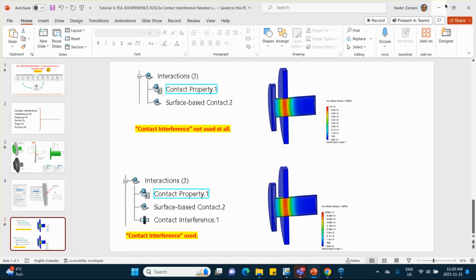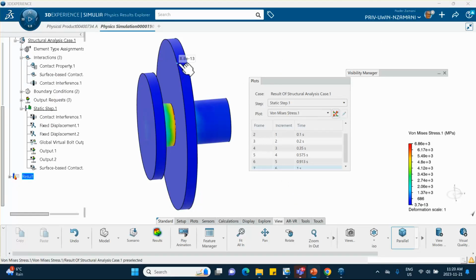In tutorial 5, I'm going to make sure that this disc is against that shaft. So there's also the possibility of that surface penetrating the other one. There's contact between these two, not in this problem though. And then I'm going to apply pressure on this face and look at the whole thing. That's going to be tutorial 5, and it requires a two-step process. In step 1, I do the shrink fit. In step 2, I apply the pressure on the outside surface of the shaft. Good luck.